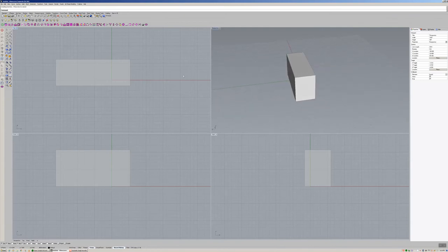All right. So again, the basics of what 3D is, you're starting with a curve. So in Illustrator, like you see the curve here. As I'm building it out, I'm circling around the object. And here, when I get to the point, it's now snapping. That means it's connecting the curve. If you leave it open, like so, and it's not connected, it's not going to create a solid object. It's going to have errors and defects. So it's very important to connect this.